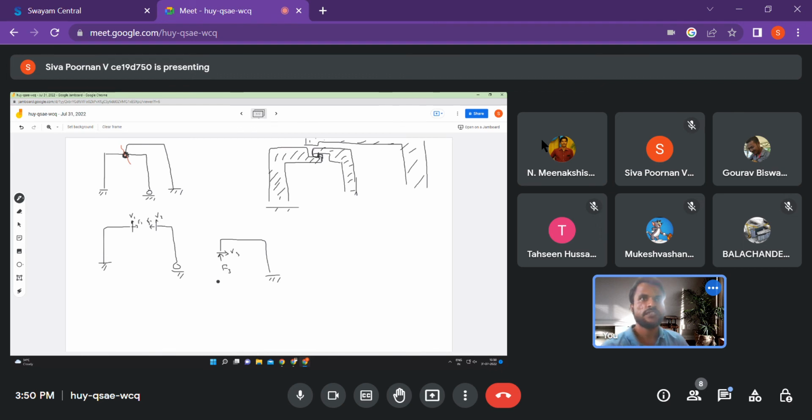So we might think that there are 2 plus 2 plus 2, 6 unknowns there, but we also know from Newton's law that the addition of all these forces should sum up to 0, right? Why I'm saying this is, if you had only one portal frame and you cut at that point, we say that we have two structures, and in each structure we say there are three unknowns, and we are not taking the other three unknowns because we know they are the negative of it. How did we know? Because if this was f1 and that was f2, we know that f1 plus f2 equals 0. That's why we are not considering f2 in the previous problems.